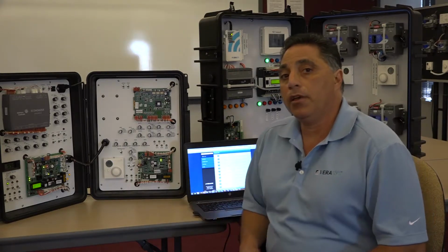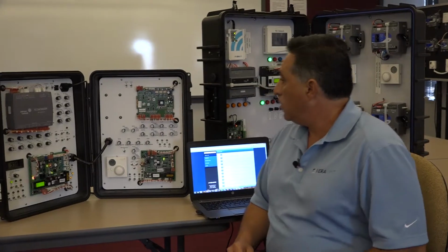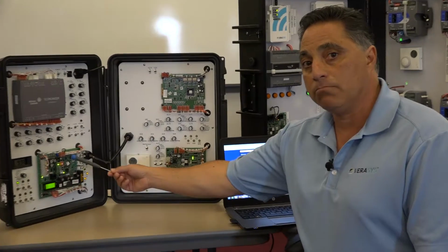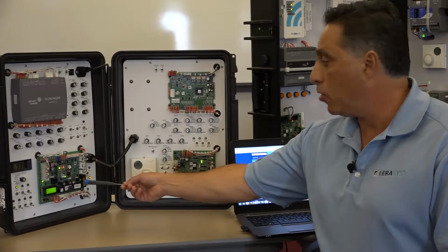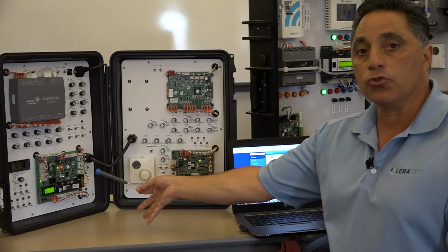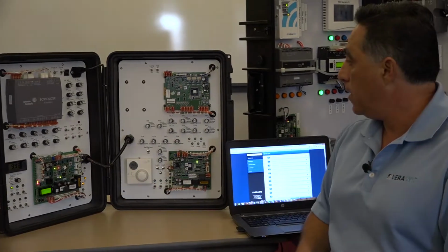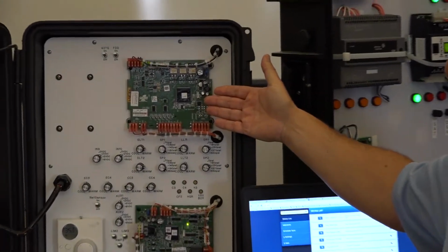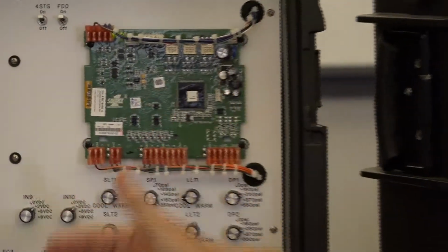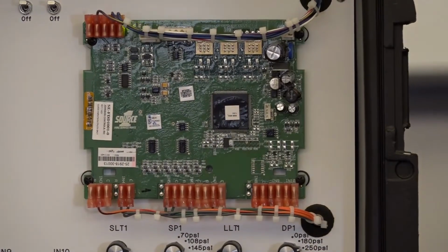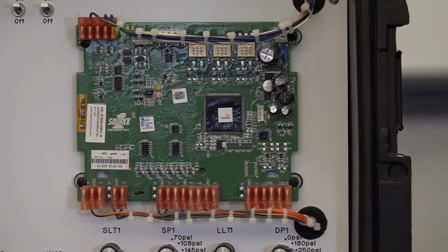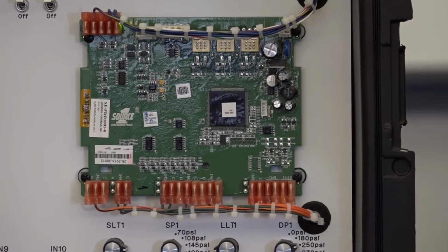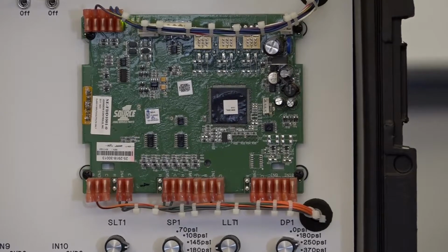So let's quickly look at the hardware itself. I obviously started with the smart equipment controller, and that's part of our rooftop main controller platform. You have to have that controller before you could have the FDD option. The FDD controller is this controller, right here that you see. It connects into the main controller through what we call our sensor actuator bus, our SA bus, and it communicates basically a BACnet communication within the equipment itself.